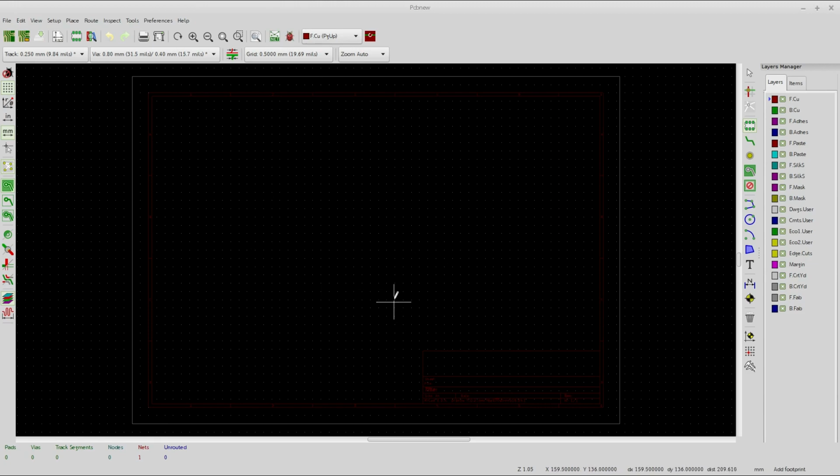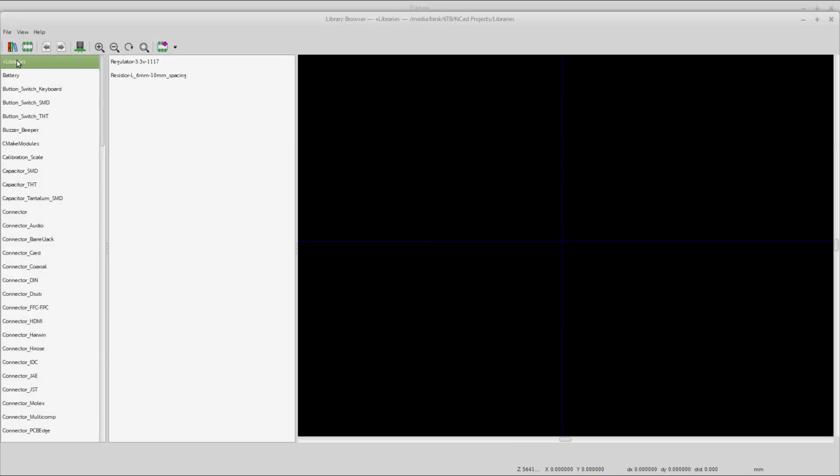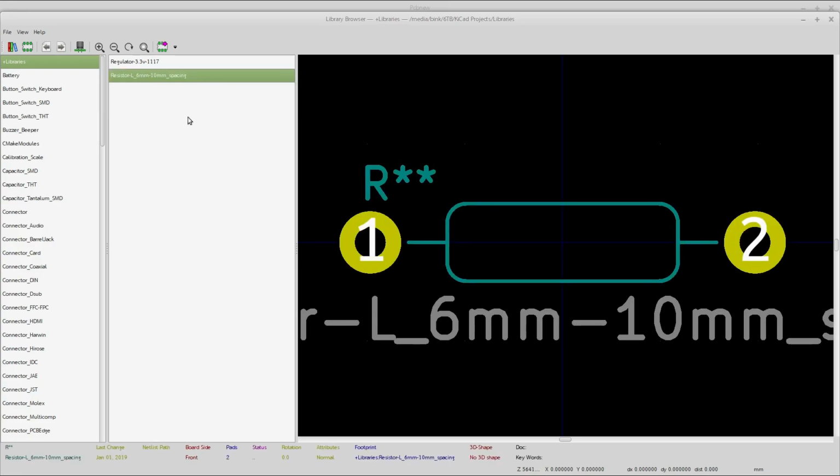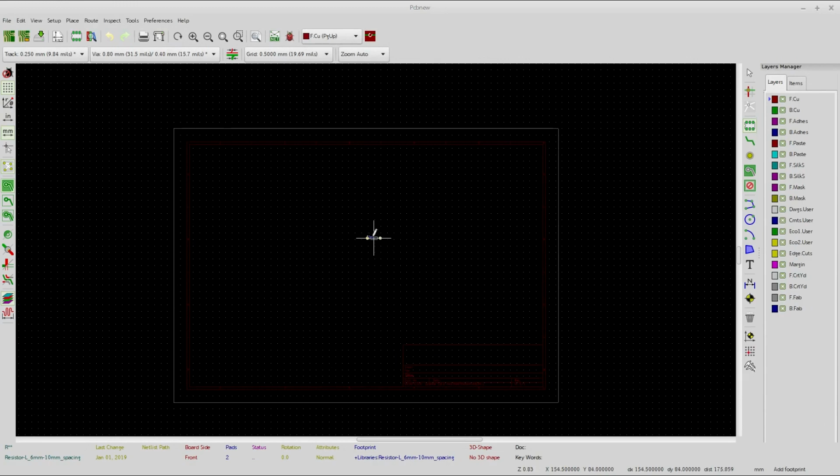That net list is then read into this, and it puts all those components out here connected, kind of, in the way that they were in the schematic, and then it's up to you to actually route them correctly, I guess. But we're just going to go ahead and place a component, and it's going to be this one right here that we made. So just double click on it, and you can stick it wherever you want.